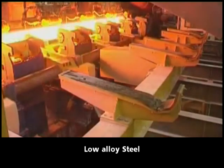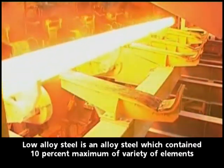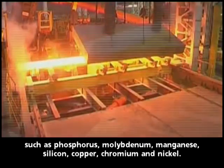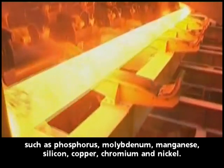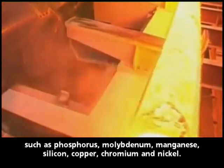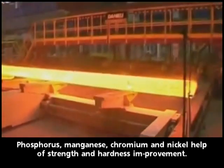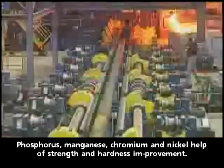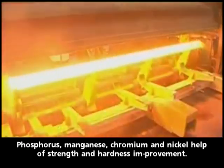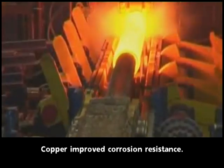Low alloy steel. Low alloy steel is an alloy steel which contains a maximum of 10% of a variety of elements such as phosphorus, molybdenum, manganese, silicon, copper, chromium and nickel. Phosphorus, manganese, chromium and nickel help improve strength and hardness. Copper improves corrosion resistance.